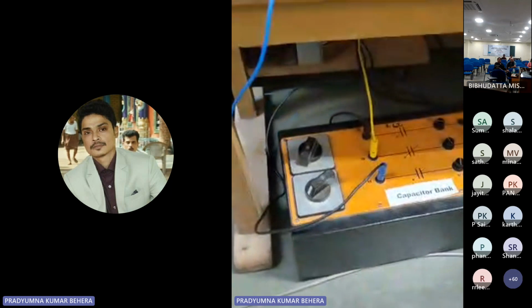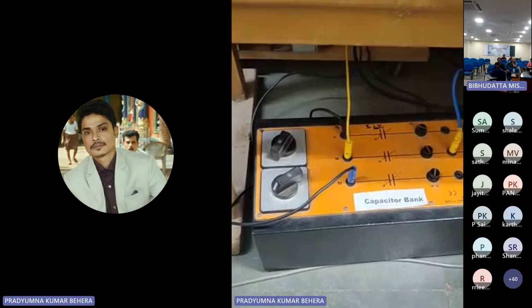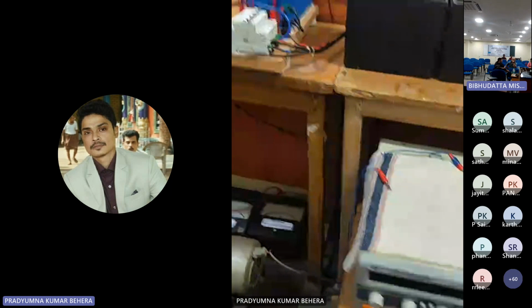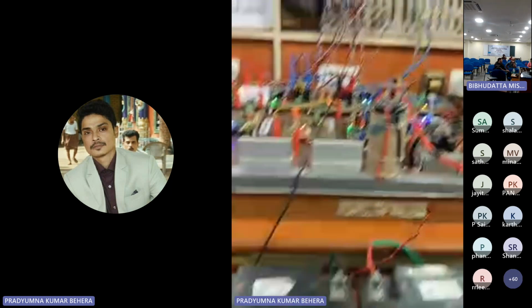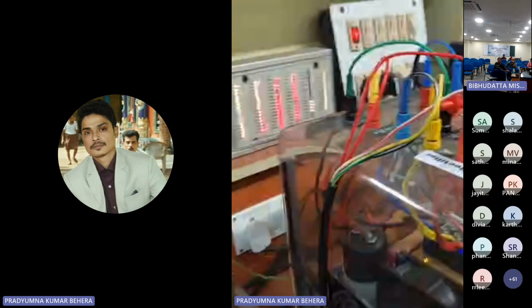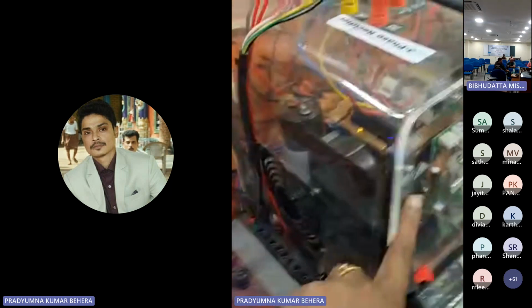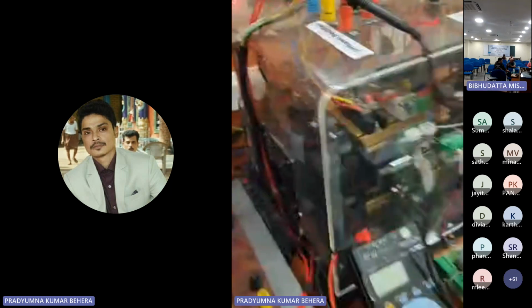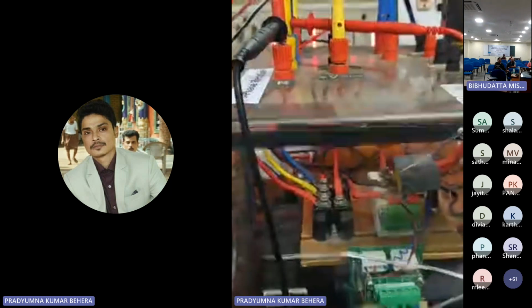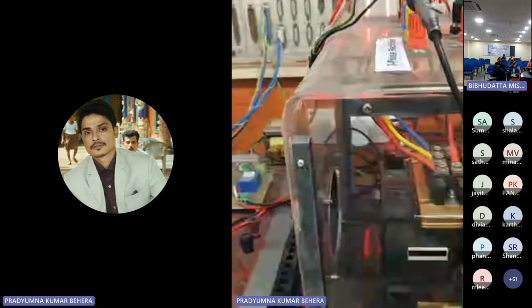And this one is our excitation capacitor connected to the terminals of the self-excited induction generator. The power output of the self-excited induction generator is fed to a three-phase rectifier. Within this converter, we have a three-phase rectifier, that is MDS 1600/100, that is 1600 volt and 100 ampere rectifier. This black switch you can see,